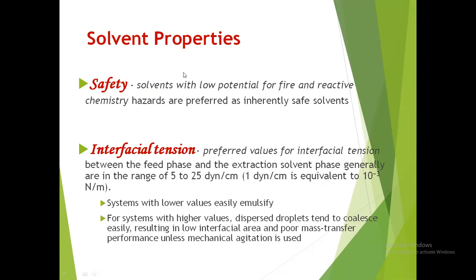Now, solvent properties, more on it. Safety: solvents with low potential for fire and reactive chemistry hazards are preferred as inherently safe solvents. So we want it to be non-toxic and low potential for fire and reactions, okay, further reacting with other components in your liquid phases.